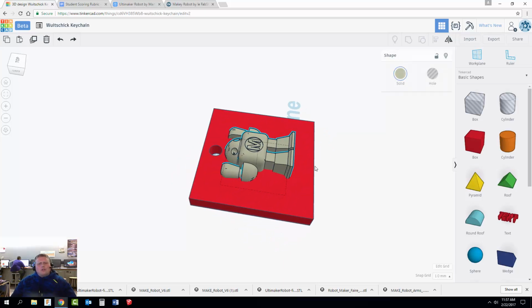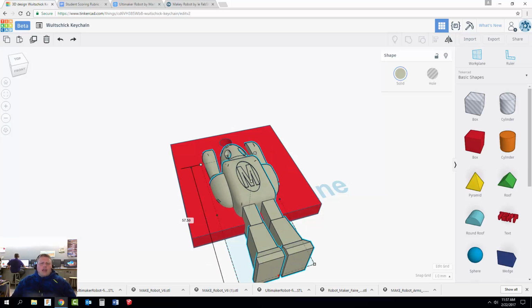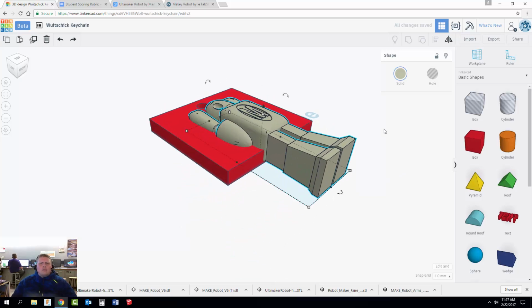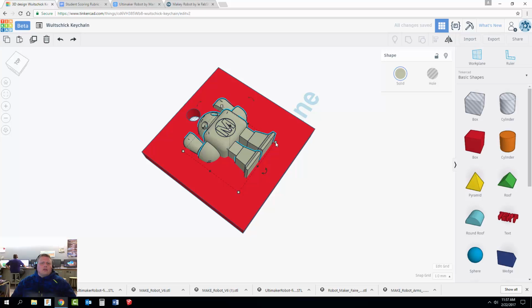And what we're going to do is I'm going to hold down Shift. Remember what I talked about distortion. If you just grab one dot and drag it, it's going to look really dumb. Really bad news, right? So what we're going to do is I'm going to undo that. I will fail you from that part of it if you do that. So please make sure that you don't distort it. And how do we prevent distortion? We hold down Shift when we scale it.